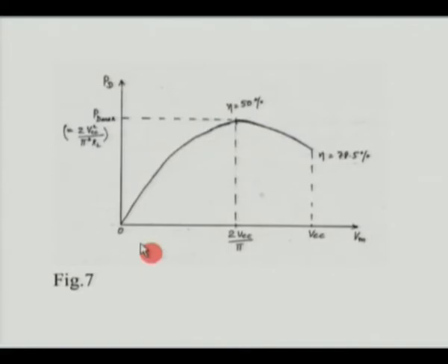So whatever power you supply, if you subtract the power delivered to the load, the remaining power is dissipated in the device. So we would see that in a class B amplifier, the power dissipation would keep increasing as you keep increasing the input voltage. Now it reaches a peak,